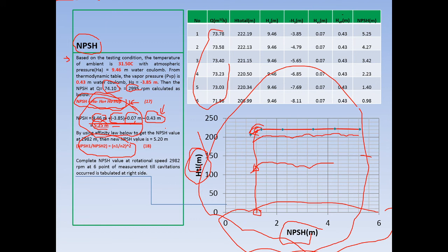But again, maybe NPSH available here is the same formula actually, like this, but without the boiling evaporating pressure. Yeah, same formula with this. But usually to simplify it, for NPSH available you just take the head of the environment minus the distance between your pump and the reservoir.